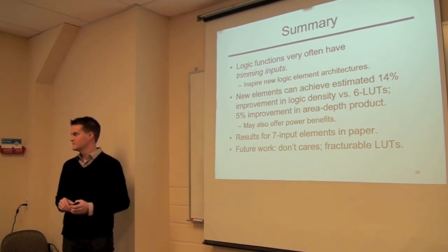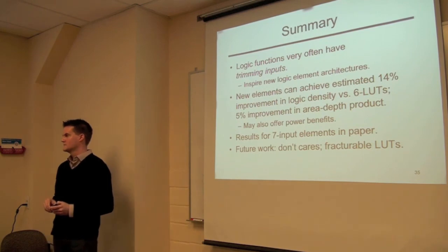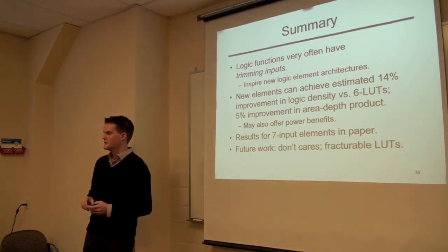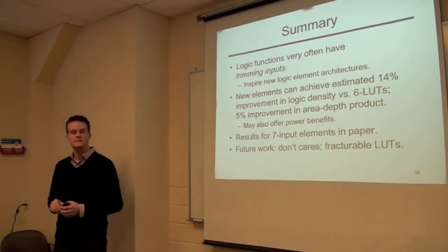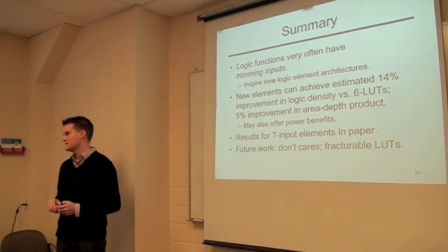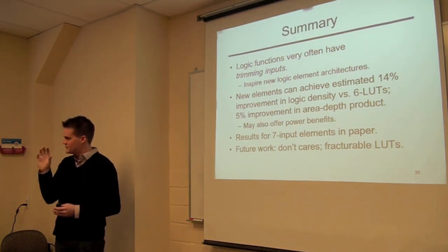Could you run through VPR 5.0 to measure the impact of the fact that your LUTs are less rotatable now? Basically just make fewer logically equivalent pins and just model it. We could do that, yes. So we would have to figure out a way, because in VPR5, if you target a cluster-based architecture, then you assume the full crossbar within the cluster.